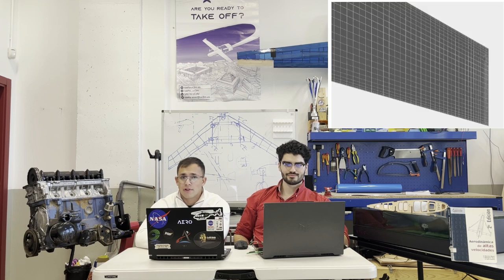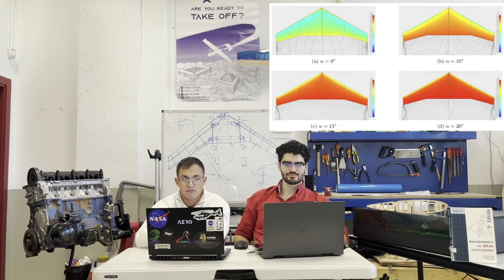This method will model the wing as a collection of surface panels, where each panel will represent a portion of the potential flow around the wing. It will compute the induced velocity as well as the pressure distribution by solving the potential flow equations while enforcing the Kutta condition that will ensure that the flow is smooth at the trailing edge.